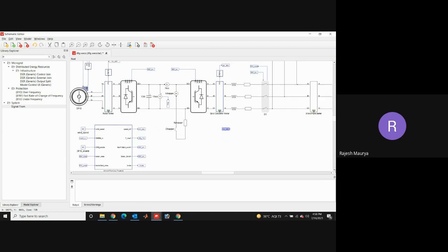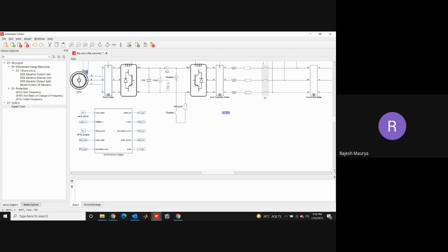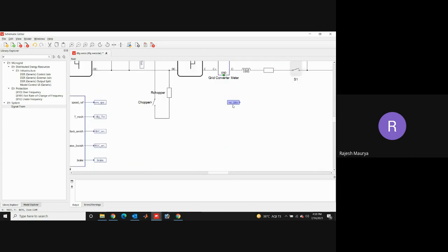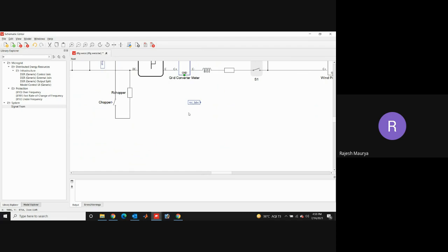So now it is matched. RSC underscore IABC. We have taken this signal over here. It's RSC underscore IABC and scope as global. Similarly, I'm going to copy this one and paste it. The same property, only I need to change the name as GSC underscore IABC.